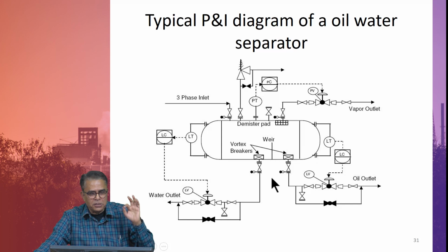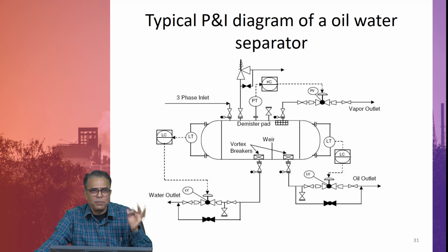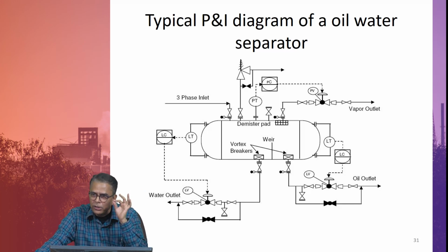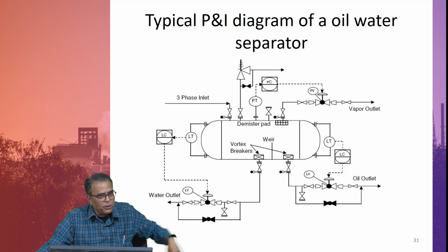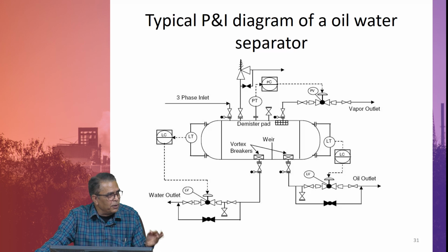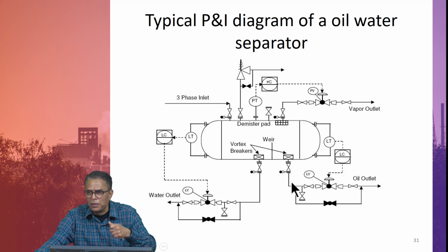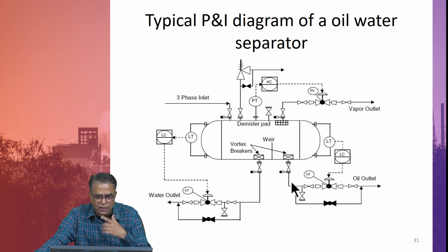All the instruments, line sizes, valves, type of valves, whether they are air to open, air to close, everything has to be brought into that, because this is the only language that is spoken among the entire team of people to be able to find the cost. So, it should be absolutely detailed enough to convey the meaning, so that clarifications are minimum. Even then you can call up and ask for clarification.